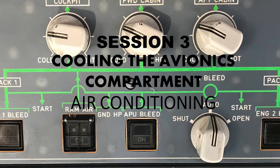Just a quick note with the computer. We have pressure switches, I mentioned there are 3 switches, and then of course you have temperature sensors. All of that information goes to the AEVC, the ventilation computer. But you also have information coming from the cabin pressure controller, the CPC, and the landing gear control and interface unit. So just so you know, there are those other sources of input into the ventilation computer.